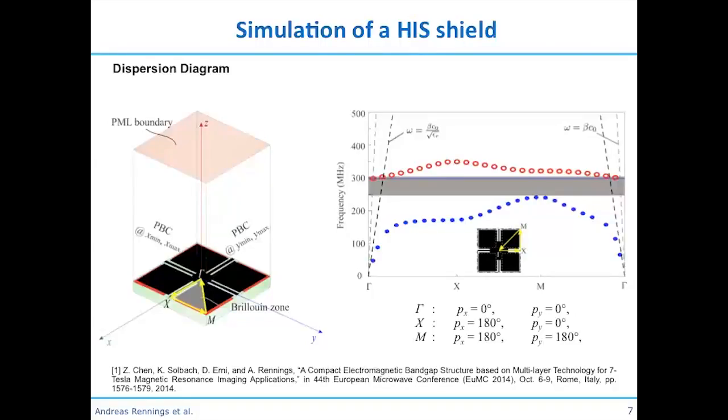And the corresponding frequency where we had this in-phase reflection, that's actually here at the frequency where this TE mode merges the light line. So that would be kind of the correlation between in-phase reflection and the stop band property.